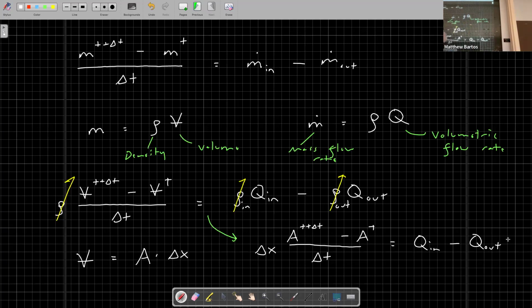Right now this is for the case where it might not be flowing full. Incompressibility will apply for both of those cases. The case where you'll get compressibility is usually with gases, which we won't be talking about in this course. But for liquids, you can usually assume that it's basically incompressible.